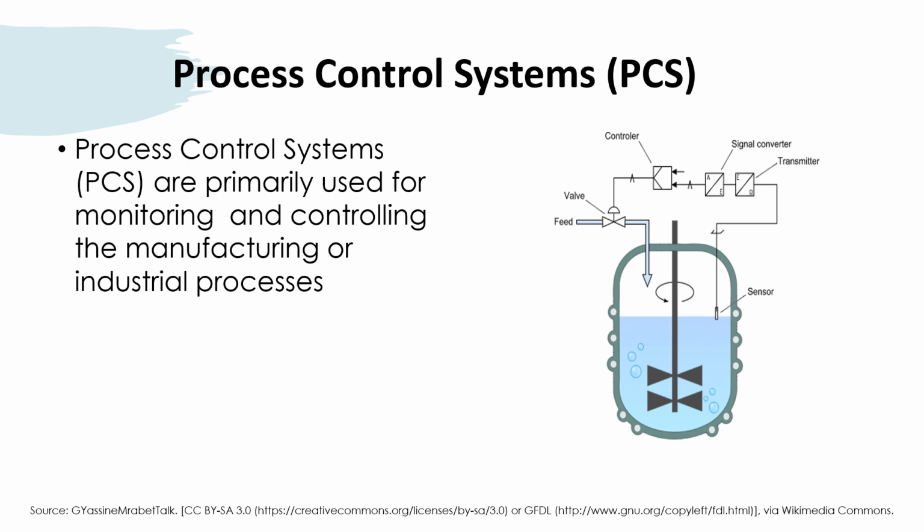In addition, PCSs are also used in conjunction with safety systems in detecting unsafe conditions and protecting humans and the environment. The figure below depicts a process control system that monitors and controls the pH level of a mixture through a sensor, an automatic controller, and a pressure-sensitive valve.